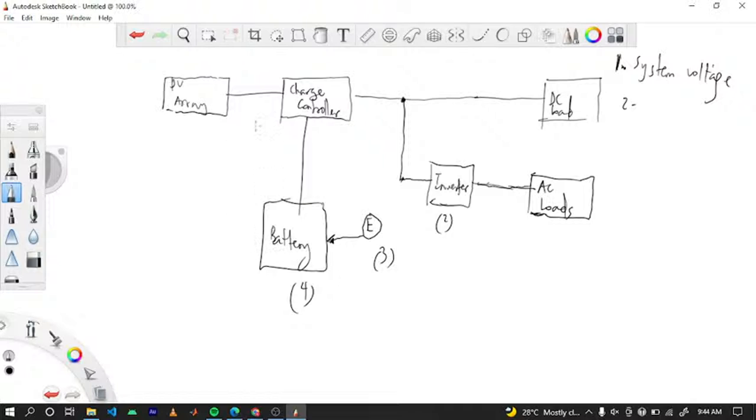Now, after battery bank capacity, we have to size our PV array. But before we size our PV array, we have to find the maximum irradiation H. This is step 5. After that, step 6, size our PV array. Step 7, size our charge control. Step 8, we'll size our protection. We'll look for the fuses. And step 9 is the cable sizing.